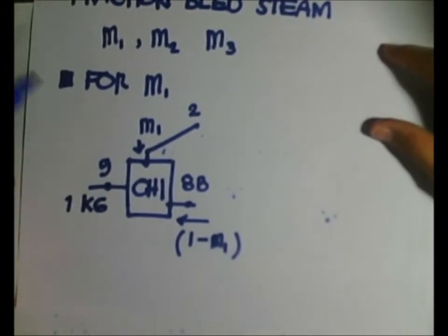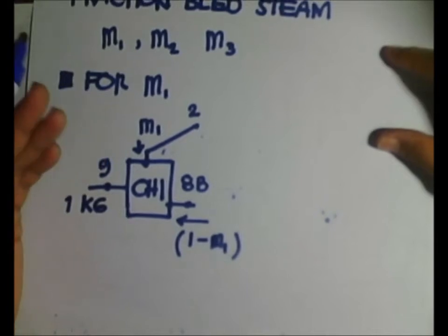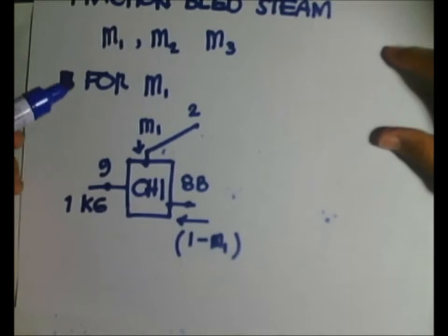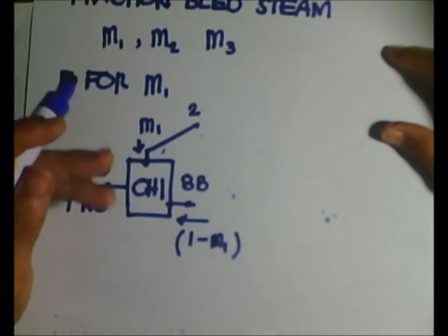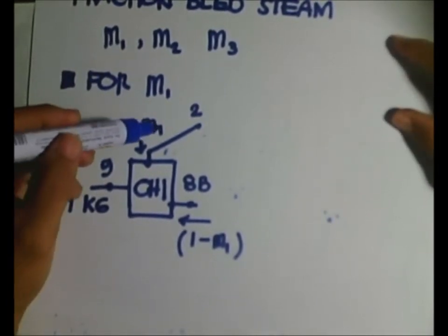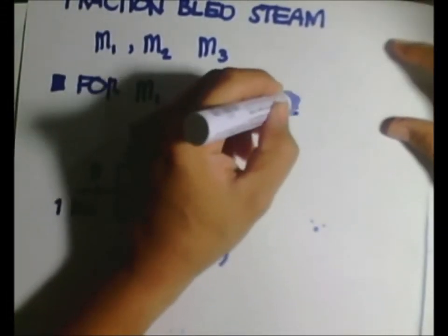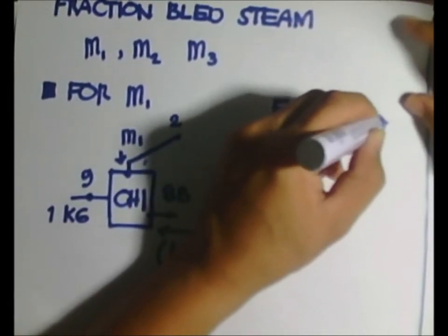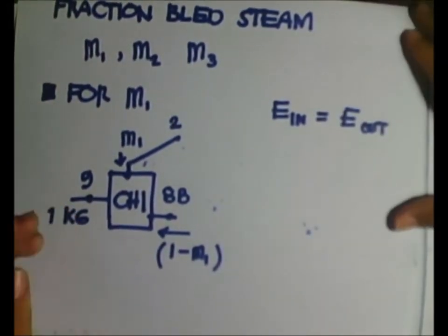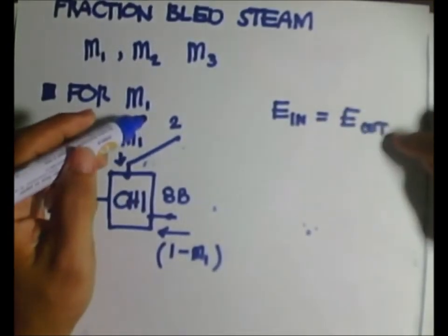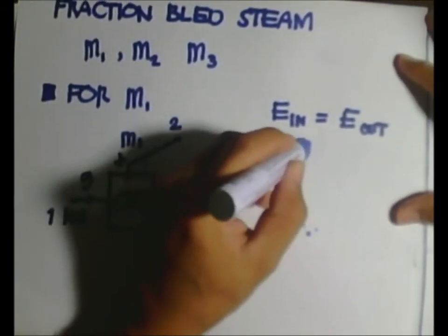We have agreed on this for purposes of calculation. Later on, we're just going to multiply this to whatever amount that we have that actually takes part in the cycle. Okay, so we do here the energy balance. So that what enters the open heater 1 is the energy balance at open heater 1.